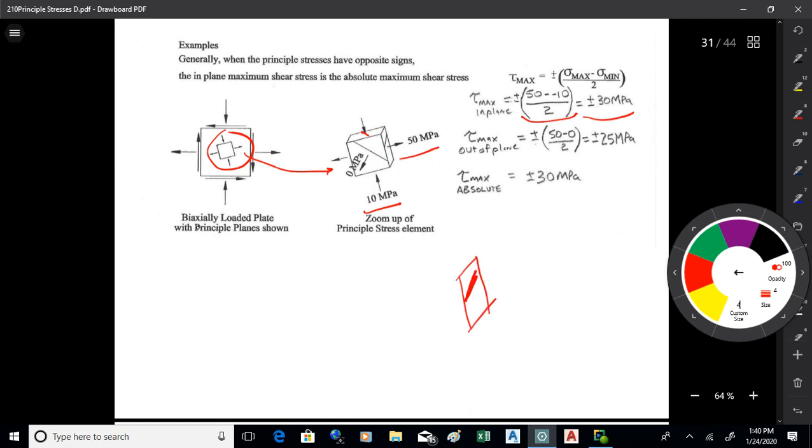But you should also consider this plane up here. That thing might shear across at 45. And what's happening with that, and I don't quite have the right one. It's the one up top, really, that I want. It would be this one here. This would be a better one to draw. Sorry about that. So we have that angled plane on the top that looks something like that. And we're going to pull on that, as you can see, with 50. Now the z stress goes that way, and it's 0 because sigma z is always 0.